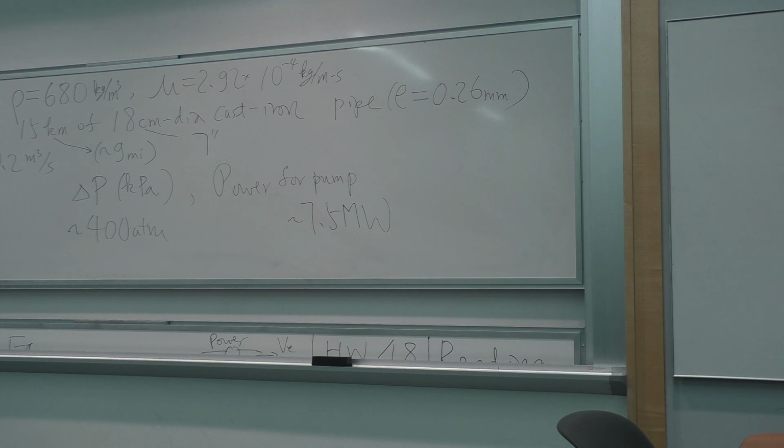Yeah? Actually, I have a question. In the textbook, it said that the bound should be 2,100 instead of 2,200 for lambda. Is that 2,100? Did I say 100? Is it 2,100 or 2,300? For the Reynolds number, for our homework assignment, we picked arbitrarily the value of 2,300. That is academic. But the actual range over which the Reynolds number can change from laminar to turbulent is something like 1,000 to 4,000. Not 100. I misspoke.